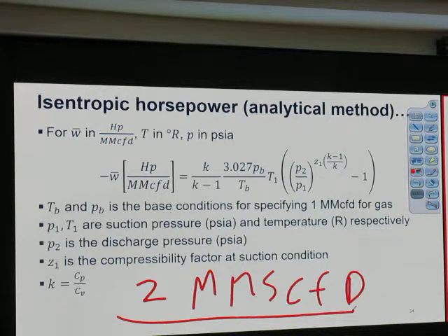I thought you said there's no temperature loss. When we have S, you see that S, that S is standard condition, we refer to 60 Fahrenheit and 14.65 for Texas, or 14.7, it depends on how we define the standard. But with that S, it means it's at a certain pressure and temperature.